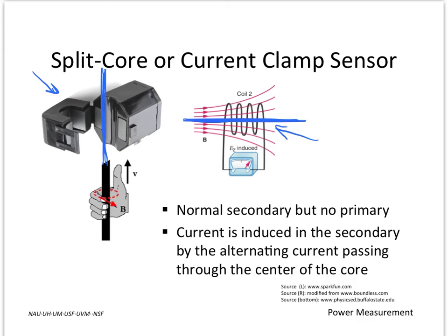This coil current, when passed through a small resistance, produces a measurable voltage that is proportional to the line current of interest. For AC power systems in the US, we know the RMS voltage is going to be between 110 and 120 volts RMS, and thus by knowing the line current, we can ascertain the power being drawn by whatever device is connected to the line.